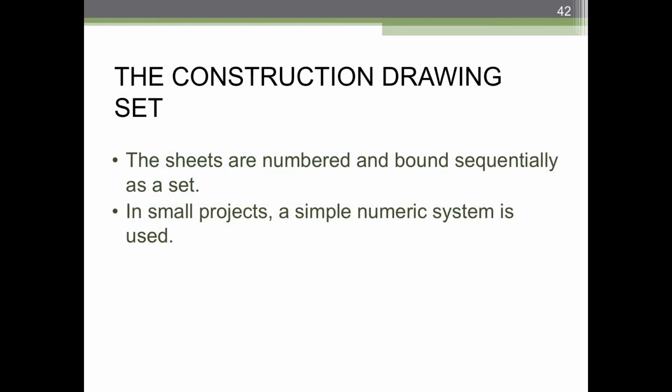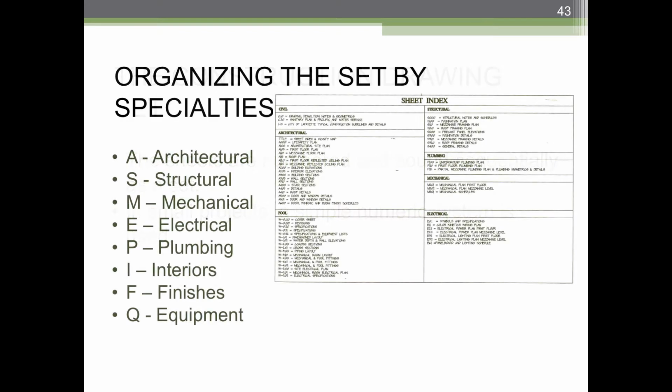Okay. Also, design factors, that's a funny thing to call what appears to be building codes. Whatever. Anyway, the set obviously is numbered and bound almost always on the left side, which is why on a sheet of construction drawings, the left side border is bigger, usually an inch. In a larger project where maybe you have 100 drawings, you need that inch just to fold the sheet of drawings open. In a small project, you can number them more simply.